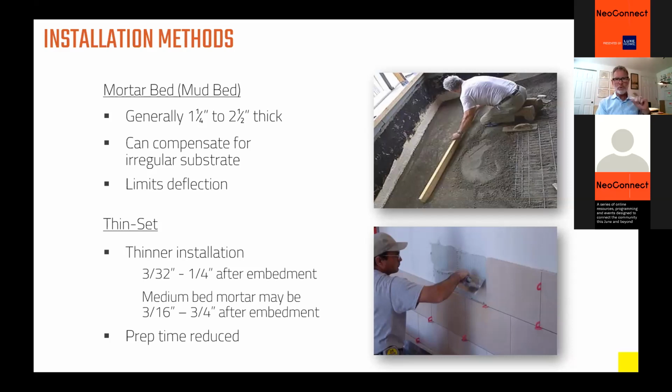And it's just like it sounds. The mortar bed or the mud bed, those are the thicker installations. Those are when you're building up a setting bed of sand and cement, often reinforced with a 2x2-inch galvanized wire mesh in the middle of the mud bed. You're building that mud bed up a couple of inches. So it's very labor intensive, but it's a really good installation. It's very durable. If the concrete underneath the mortar bed is not perfectly flat, that's okay, because the mud bed will compensate for concrete that's not flat enough. And you're adding stiffness to the floor also, so we're reducing floor deflection.